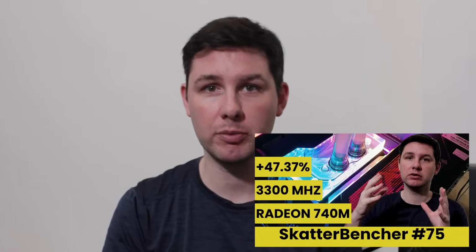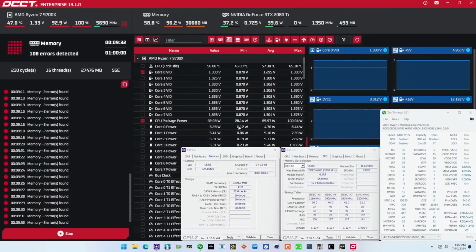For the Hawkpoint APUs, I had to adjust the TRS timing a little bit to get rid of some annoying green flashes, but other than that, the memory was stable. However, for this system, the memory is stable for the benchmarks, but it doesn't pass the OCCT memory stability test. So I wouldn't consider this a stable system. That said, it serves a useful purpose for this guide to illustrate the performance improvements from tuning memory timings. I'll figure out the root cause of the instability in later guides.